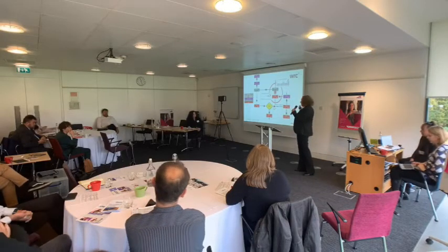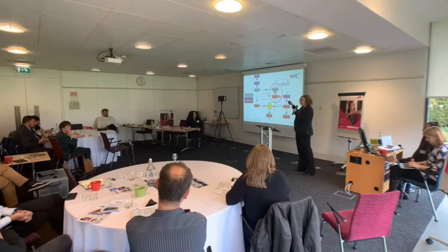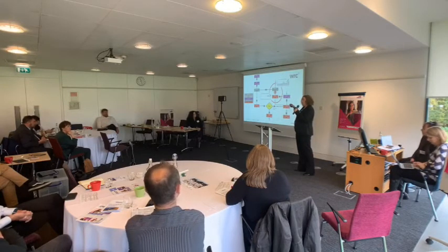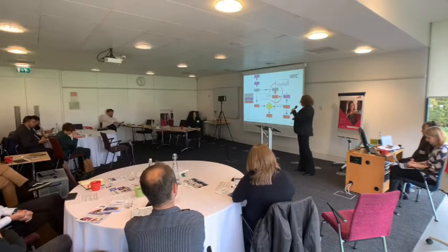And this is why I think upstream work is so important, because what's the point of chasing leaks in DMAs if there are actually problems either at the meters or upstream? And you wouldn't know just by looking at the DMA flow.